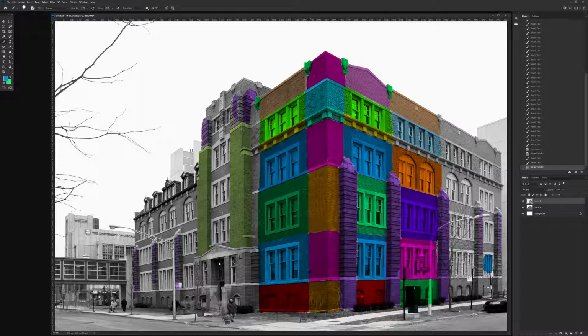If we have a continuity error in the height of the second story, so here where I've got green and orange and purple, I'm going to need to make sure that the height of each of these meshes is identical if I'm going to be able to snap them together and continue to make another story above. I also need to make sure that they're going to be identical in lying on the zero plane so that I'll be able to snap them to another story below. So that part is going to be really, really important.